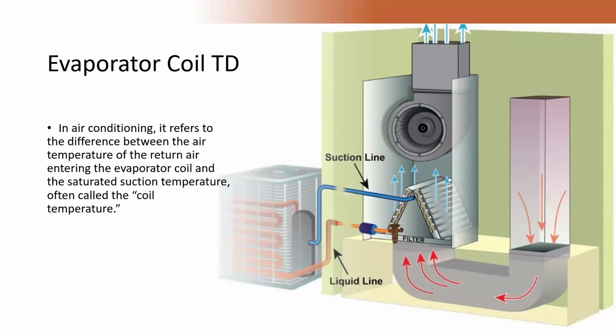So an engine that is starved of fuel won't work properly. A sprinkler that doesn't have enough water flow will not work properly. A duct that is kinked or undersized will not work properly. These are all the same parameters we're looking at when we're looking at the refrigerant mass flow rate of that compressor. If we can't move the refrigerant, we cannot add or remove heat, because that's what we're doing. We're adding and removing heat.